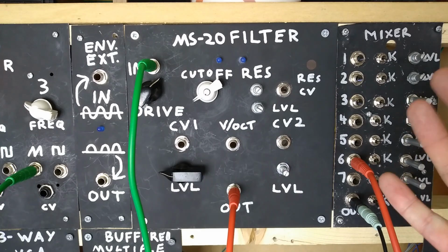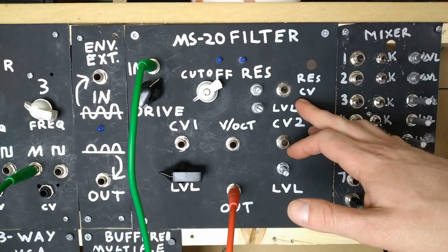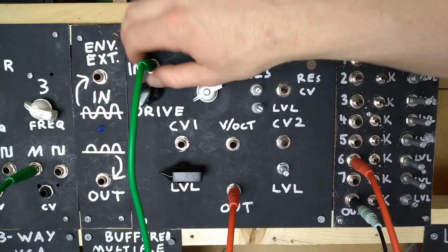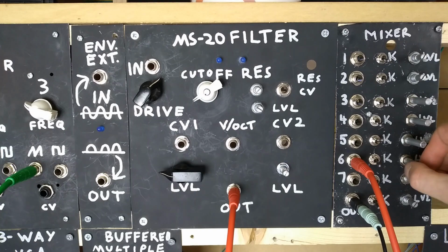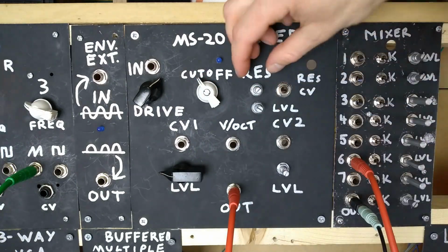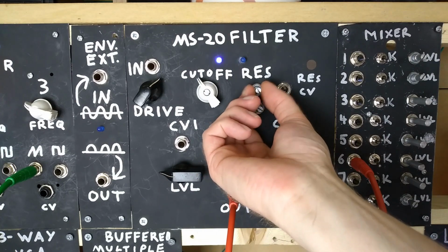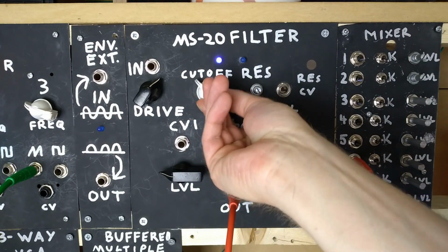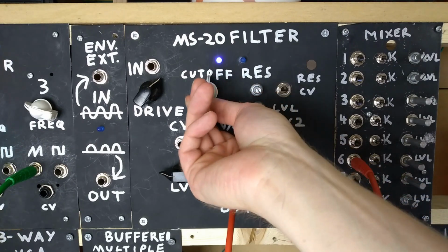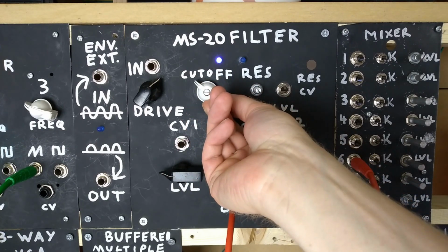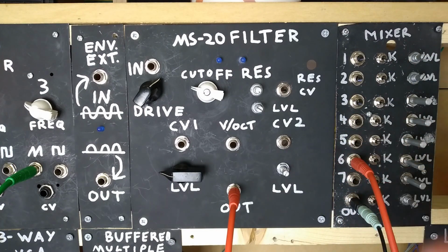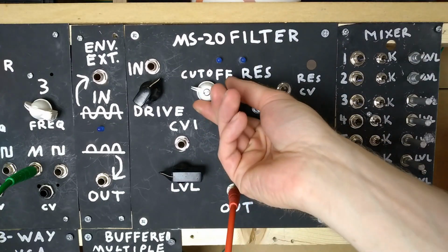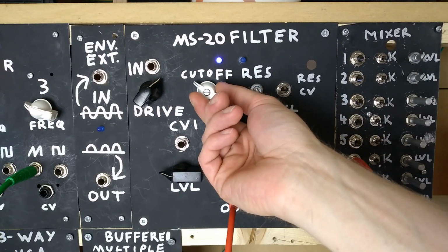So while we're talking about resonance, I think we should demonstrate the resonance control voltage. So for that, we don't even need the input signal. We can just pull that straight out. And I'll turn this down a little bit, just because the resonance is very loud. So I move the cutoff to just about there. So now we have pushed the filter fully into self-oscillation. So it's basically creating a sine wave, and we can adjust the frequency with the cutoff.